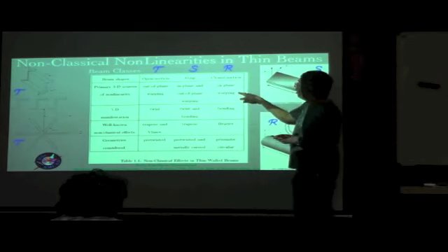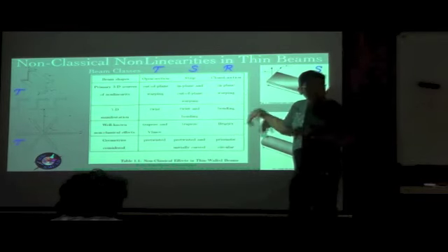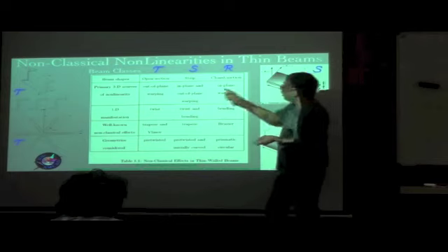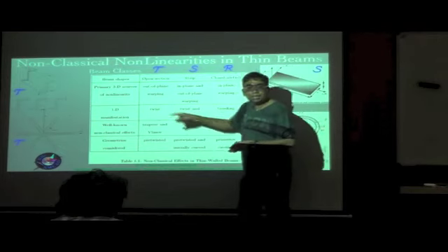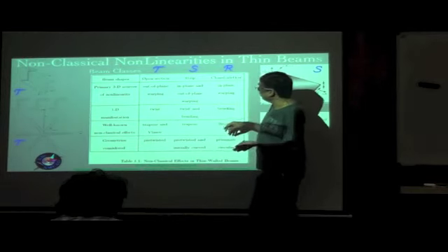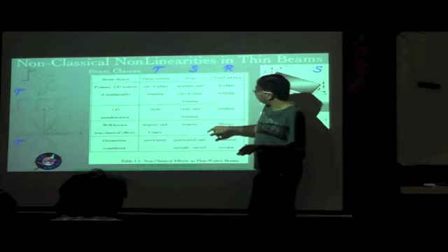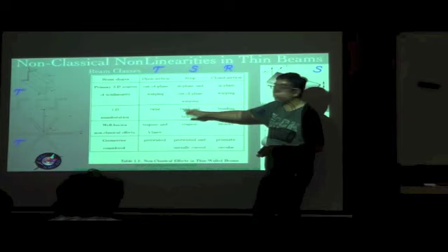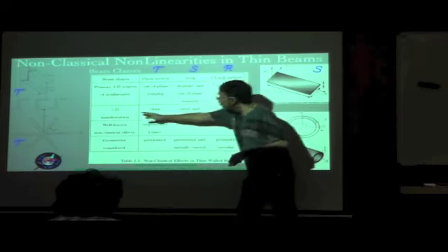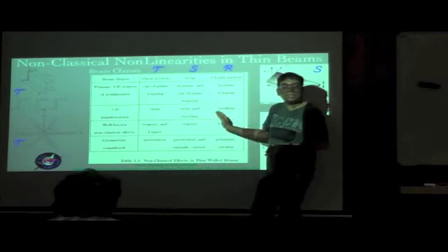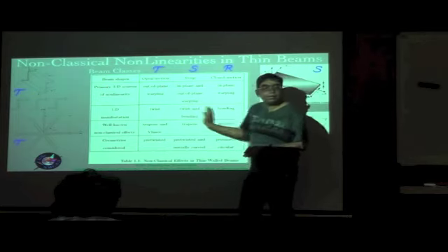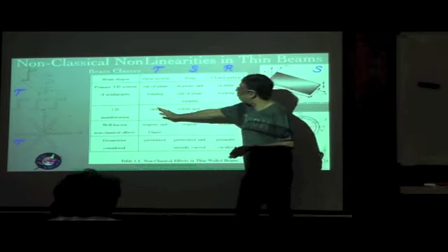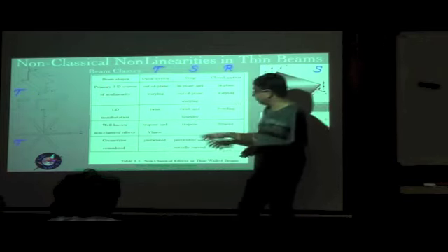Again, the in-plane warping was dominated by bending, as we showed in the Brazier effect, whereas the out-of-plane warping was dominated by twist. In the case of the strip, the in-plane and out-of-plane warping are due to a combination of twist and bending. So both come into the picture over there. Once again, in terms of the 1D manifestation also, you can see that the strip acts like an interface between the open section and the closed section.